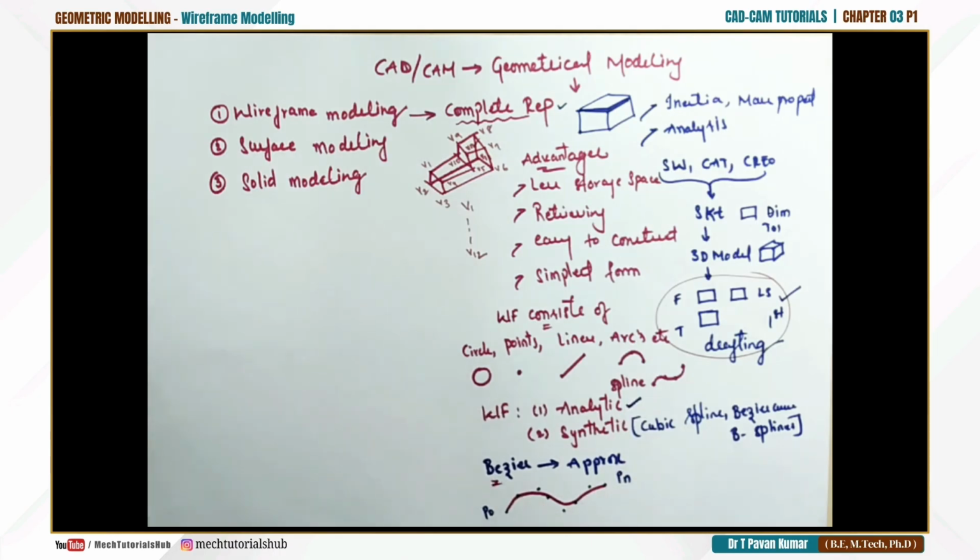Bezier curve. Here again the curve can be controlled by using any of the control points. If I consider a B-spline, if I have a number of control points, something like this, the curve can pass through all the control points. So that is the reason we say the B-spline has an option: it can be used for approximation like Bezier, as well as, if we consider this curve, it is passing through all the control points.